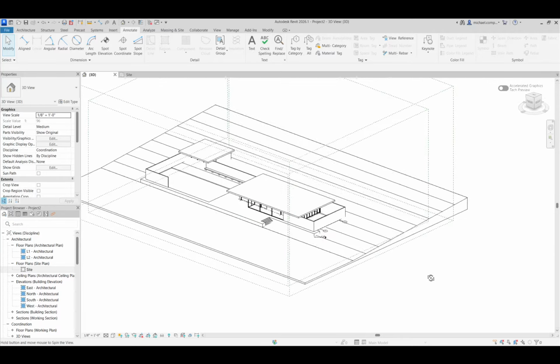But as you can see, the ground is starting to come through the building. Actually, I'm going to put that up a little higher to exaggerate that point. So let me select this one more time, modify, put that up at 8 feet. Okay, so now you see how the ground is coming through the building. I'm going to turn on a shaded view, specifically this, so you can see where the green is cutting through. Now, obviously, you can't have the site like that; in real life, you would excavate the footprint of the building.